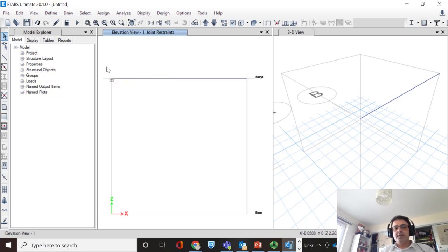you will see this point is a kind of fixed support, and this point is free, but I just want to use this point to deform just in a 2D plane for me. That's why I just grab this point as well, and see this is the X and Z axis.